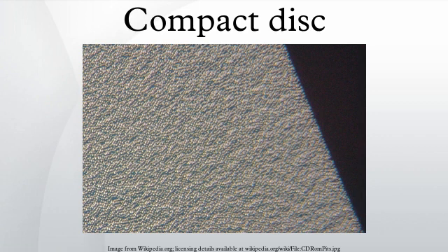A thin layer of aluminium or, more rarely, gold is applied to the surface, making it reflective. The metal is protected by a film of lacquer normally spin-coated directly on the reflective layer. The label is printed on the lacquer layer, usually by screen printing or offset printing.